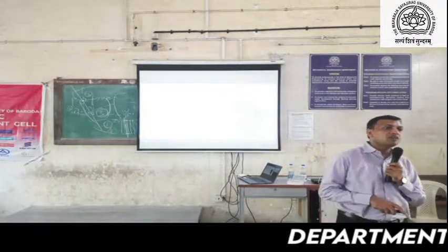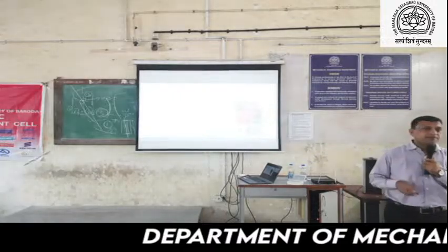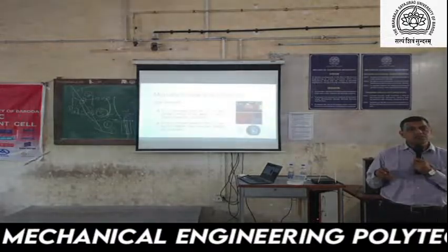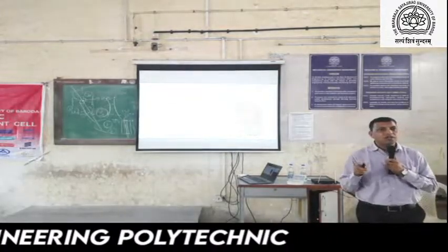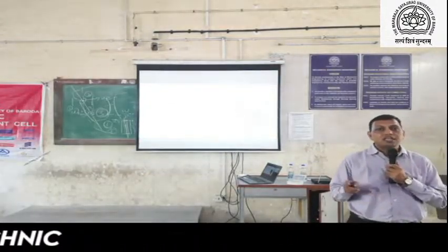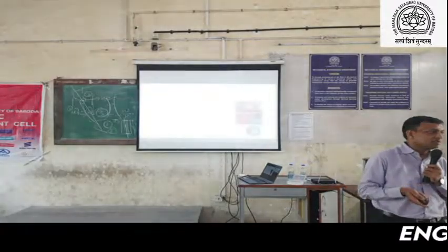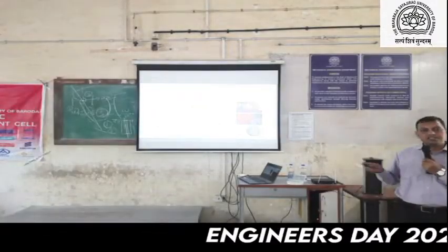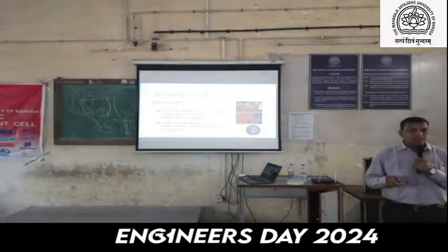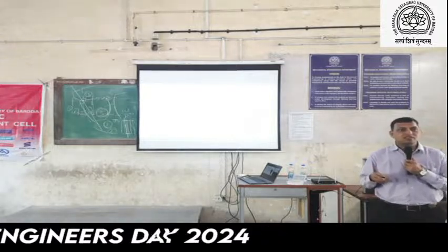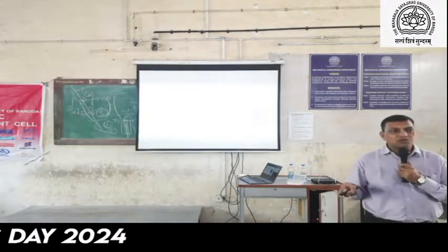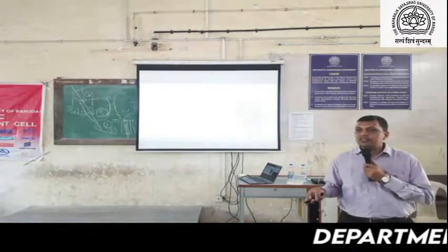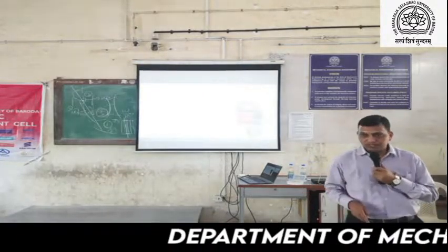In case hardening, we just harden the tooth area. Means the tooth area which comes in contact should be hardened to a particular depth. That is related to the module as well as the application, how much case depth we require. For that reason the heat treatment cycle should be considered. If we require some particular depth X, then a related time Y should be considered. So if the X value increases, the Y value also increases in the heat treatment process.